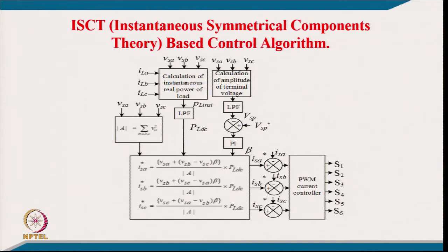Of course, we already discussed earlier in some algorithms that those line voltages may be distorted or unbalanced. So, for avoiding the distortion, we have to pass them through a band pass filter, so that only the fundamental components of these voltages are achieved, and after that we convert them into the phase voltages. In these phase voltages we have to find only the positive sequence voltage, which is a balanced set of voltages, and those we use. From the load current and the phase voltage, after multiplication we get the instantaneous power, and after the low pass filter we get the load power.